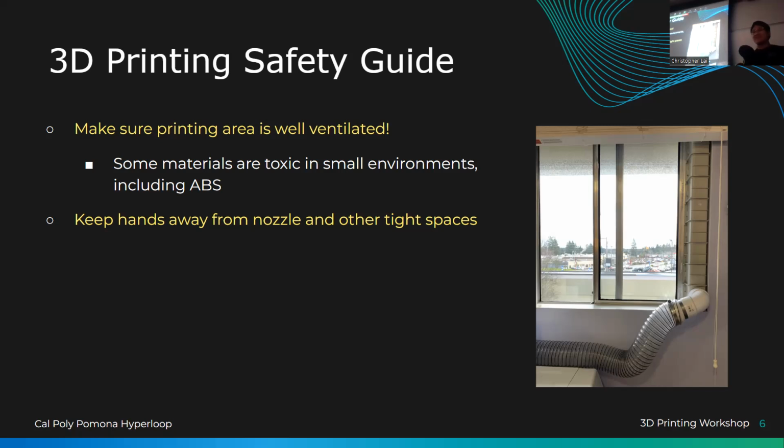That last one's very specific, but nozzle replacement, and if there's one thing I want you to take away from this workshop, is that you want to install your nozzle when the hot end is hot. You want to remove your nozzle when the hot end is hot. Because what you don't want to do is remove the nozzle when it's cold and the nozzle's snapping on you. Because the nozzle is made of metal, and this metal is kind of brittle, right? It's not the strongest thing in the world.